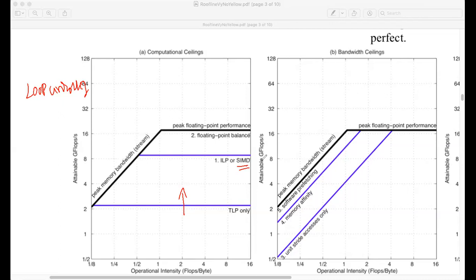In a processor, the SIMD length is always fixed: six multiplications in parallel, or 8 multiplications in parallel, or something like that. Since it's an ASIC, the SIMD length is fixed. But in an FPGA, you can unroll it and configure new things on the fly. On the fly means at design time. Because of that, it's what you can achieve.